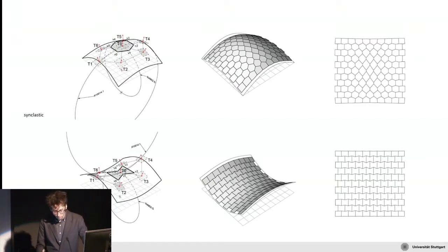So in this case, there's also a lot of research going into the geometry, and I think that applies for all these kinds of construction and structures. Having, by the way, a double curved surface in general gives the whole building a lot more structural stiffness. So we're not building these weirdly shaped buildings just because they look cool, but because they actually have some structural performance, because they, to some degree at least, follow the main load-bearing direction. They are structurally optimized, but at the same time, of course, there's a design intent, so they negotiate between the two.